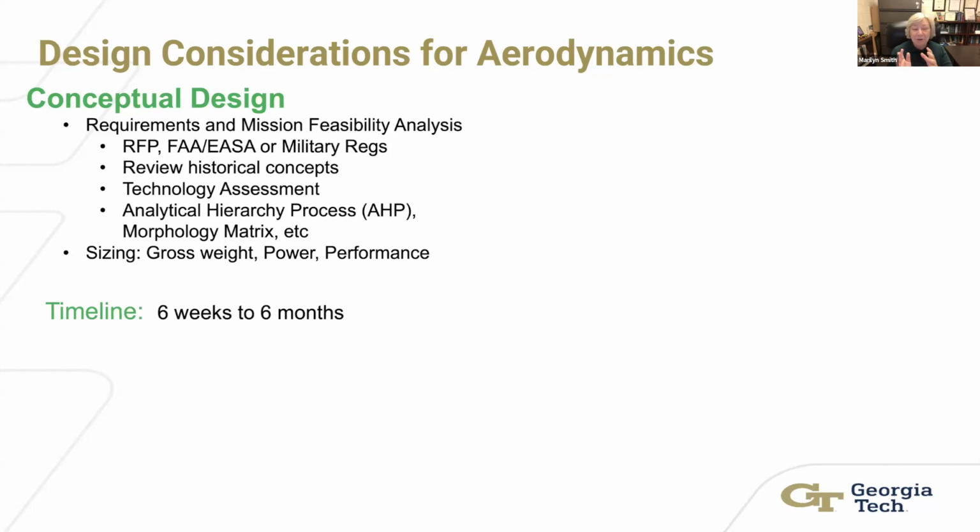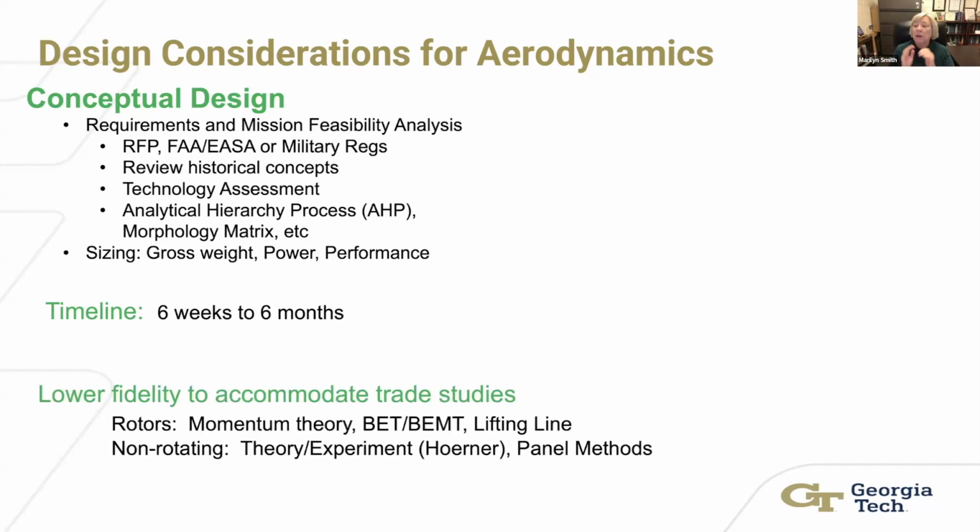GoAERO is what you're going to work to. But typically you'll use 6 weeks to 6 months. For more complex designs, you need to go farther out. More simple designs are closer to the 6 week side of the house. Please do not rush out and try to do RANS CFD for this part of your design. You need to be doing a lower fidelity effort. You need to be doing trade studies.